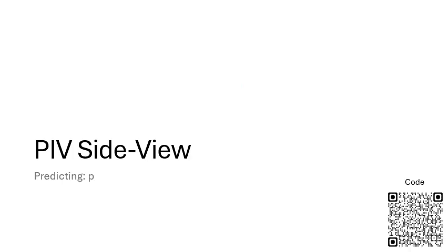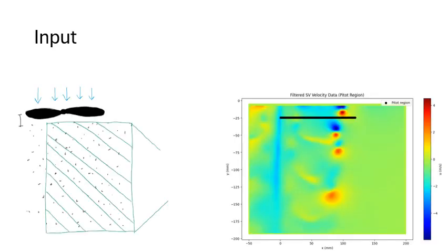So I took these principles and said, okay, what if we apply this now to real PIV data? We're going to predict a pressure using velocity inputs at whatever resolution we're given, and it's going to learn a pressure field by using the X and Y momentum of the Navier-Stokes equations, as well as the pressure Poisson equation from earlier.